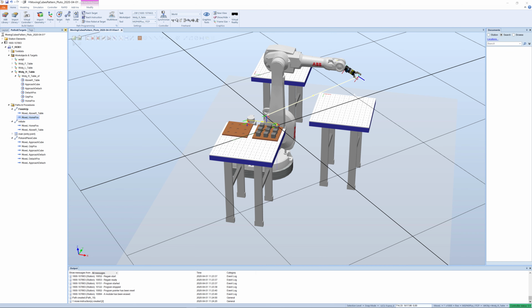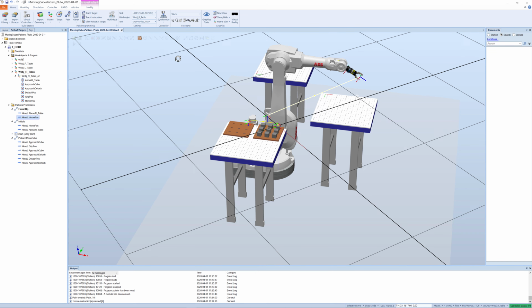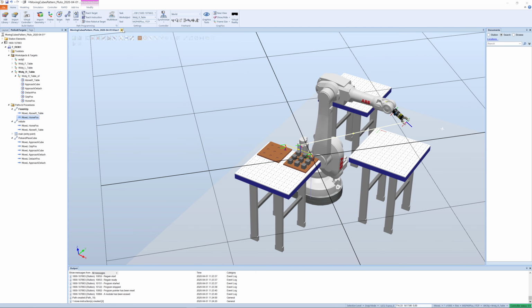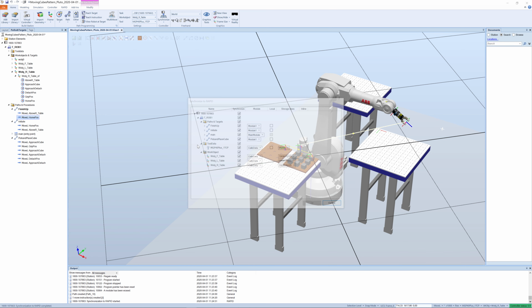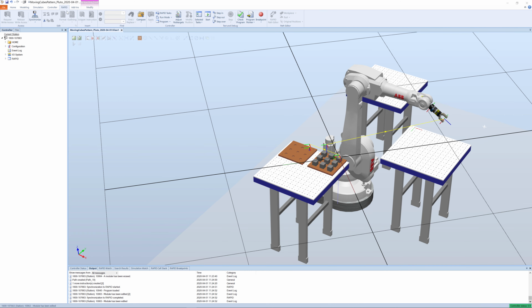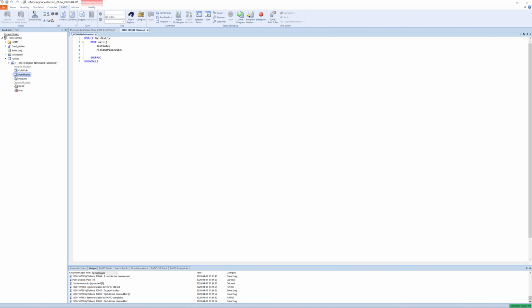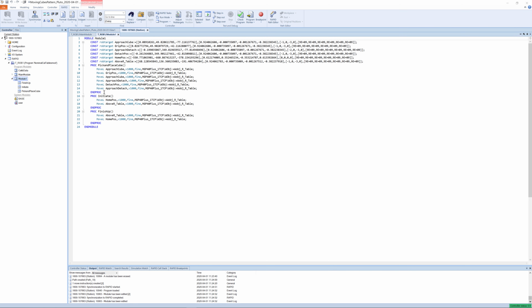And after this, we just check that everything is working as it should in this simple program, and do a synchronization to Rapid. Create the program like this, and go to the Rapid tab, open up the Rapid, and check the main module. That's fine. Well, we miss actually one thing here. Strange. Did it first also. We need the finish up as well.